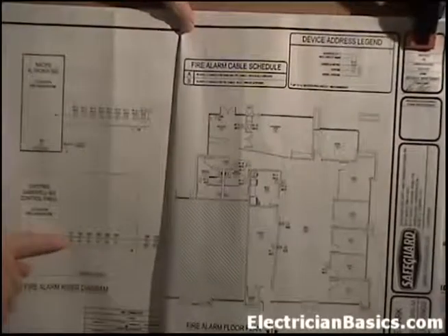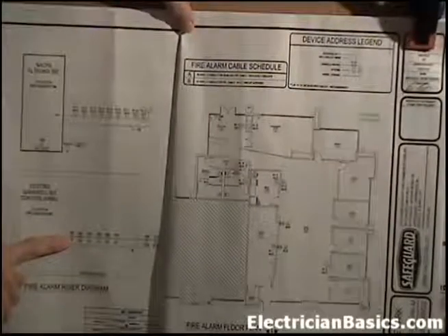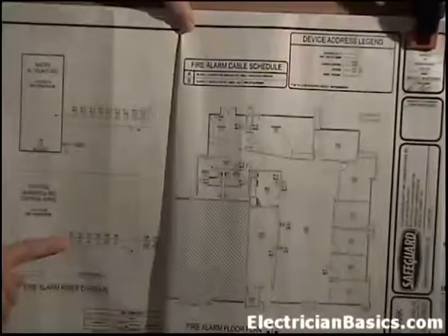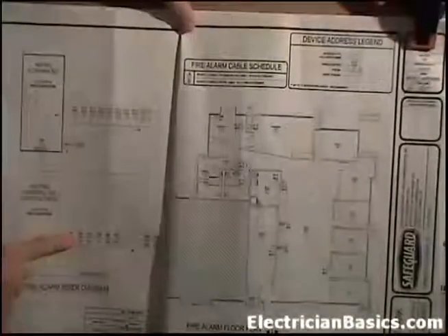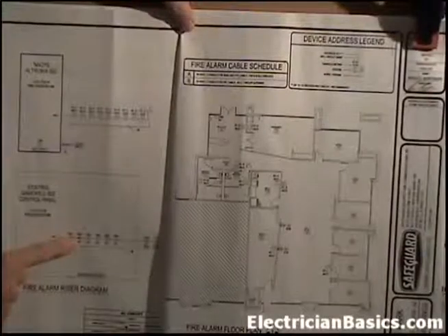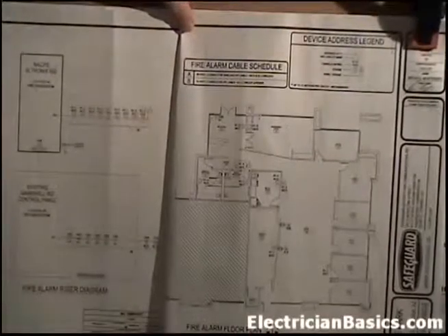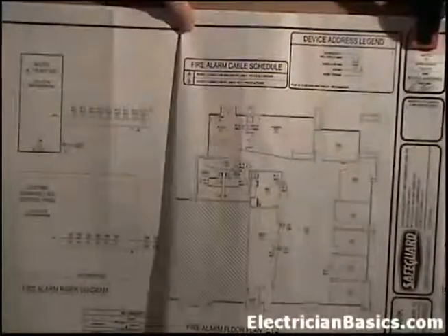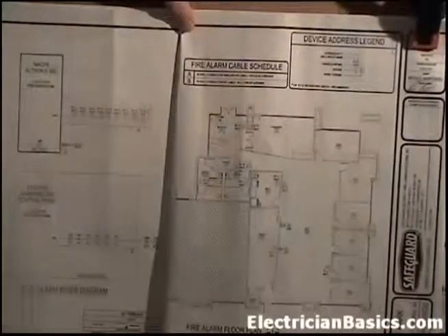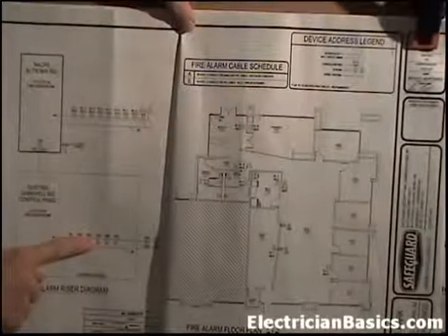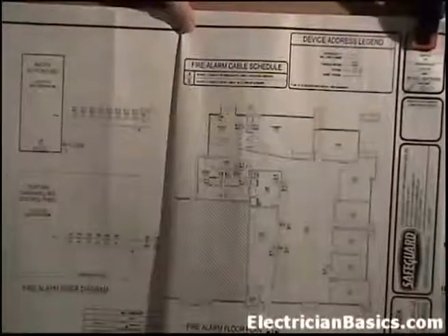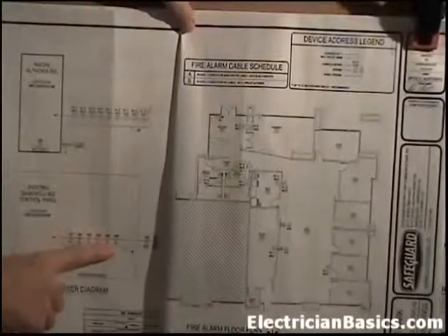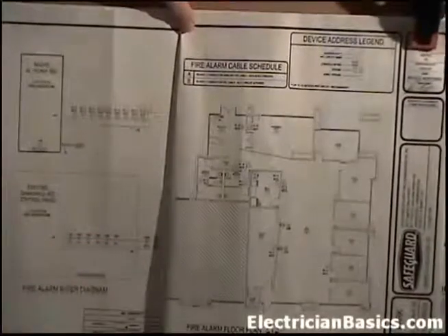Okay, well, the first one in line is 1001, has like an S and a little hexagon. That's a smoke detector. It says exterior. 1002, kind of like a W, and that's water flow box. Now these symbols again are on the previous page, FA01. This next, the third one, 1003, has kind of like a T. Okay, that's a fire sprinkler tamper. Okay, that's 1004 is like an F. That's an addressable manual pull station. 1005 is like an F, and so is 1006. Addressable manual pull stations.